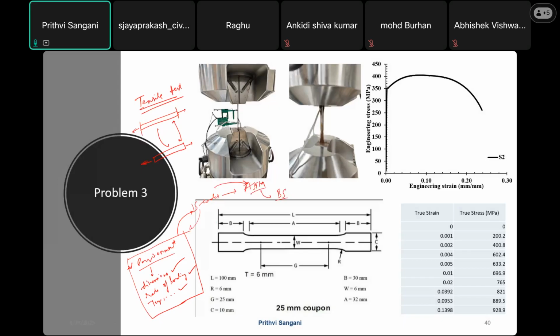For example, you keep testing compressive strength of cubes and cylinders. Why only 150 by 300? You can say it is because of size effect, or because of Saint-Venant's principle, your length should be at least two times your diameter so that you will not have any stress concentrations. But you can also have 200 by 400 cylinders. Or why only a 150 by 150 cube? That's a generic way of doing it, a generalized way, because if you are testing your concrete,